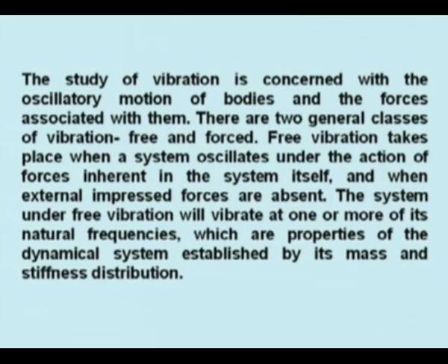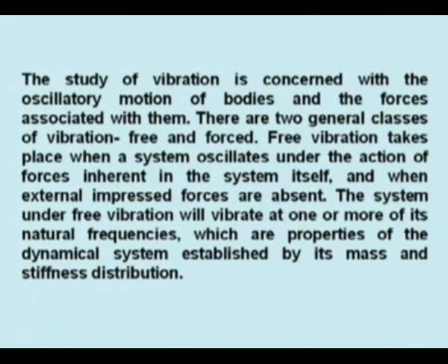The study of vibration is divided into two general classes: free vibration and forced vibration. Free vibrations take place when a system oscillates under the action of forces inherent in the system itself and when external impressed forces are absent. If there are no forces, then the body will obviously be in equilibrium.